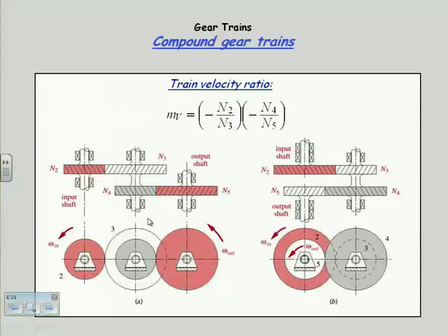And this would have the same direction of motion, because in effect this center pair is acting as an idler as well. I could package this differently such that the input shaft and the output shaft are collinear, which is a very handy thing from a packaging standpoint because the shaft appears to go right through the transmission and out the back side, but it doesn't in fact do that. It goes off to the side through this countershaft and back.